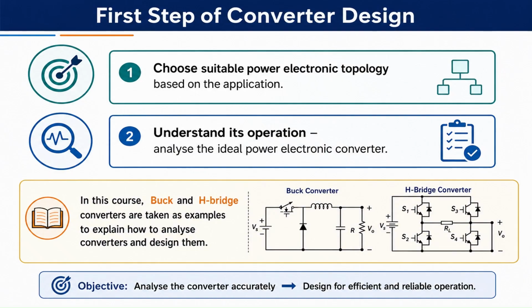So a buck converter solves this problem by using high frequency switching devices. Instead of wasting energy, it transfers energy efficiently from the input side to the output side. So this is the reason the buck converter is preferred in modern power electronic systems.